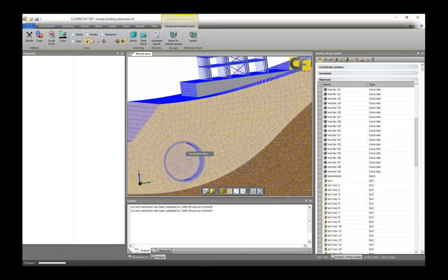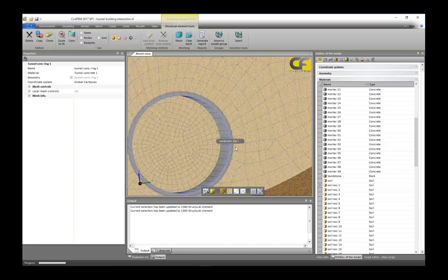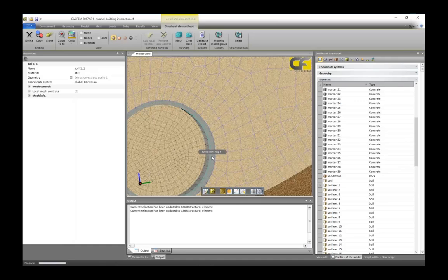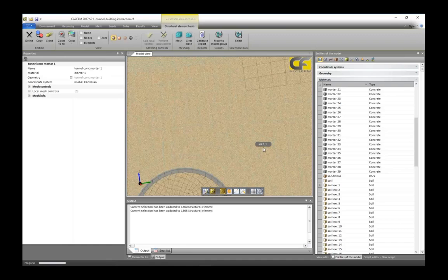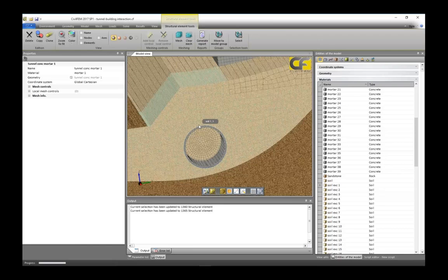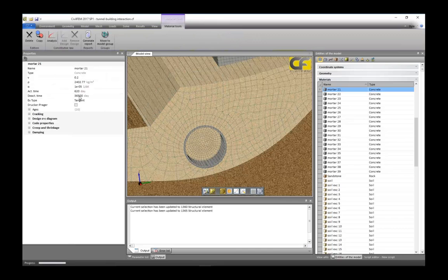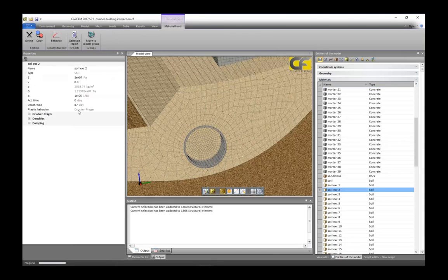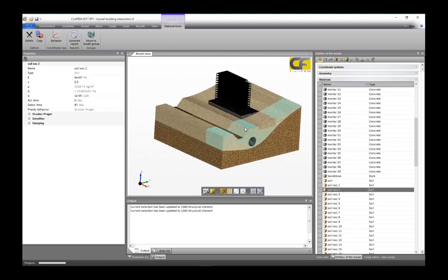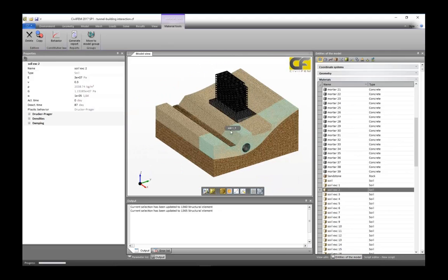We are excavating different parts, and we have here the rings of the layer, the different rings that are placed when the tunnel is constructed, and between the precast rings and the soil, a mortar is injected. This mortar has different times for activating and deactivating. So what we do is generate the different parts with different materials. In these materials, we add different activation times, and we solve for different calendar times. And in this way, we solve the tunnel construction process.